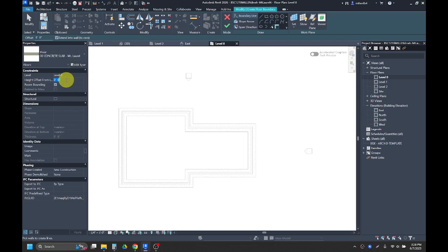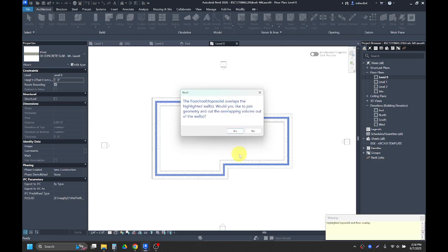And I'm going to give it an offset of, say, let's say I'm not making this a full basement area. So I'm going to bring it up about 4 feet, maybe even I'll do 5 feet. So I'll just have like a crawl space area from it. I'm going to hover over one of my foundation walls and then tap the tab key and then click to do the chain of them. And I'll want this on the outside of the wall, and I'll click the green check.